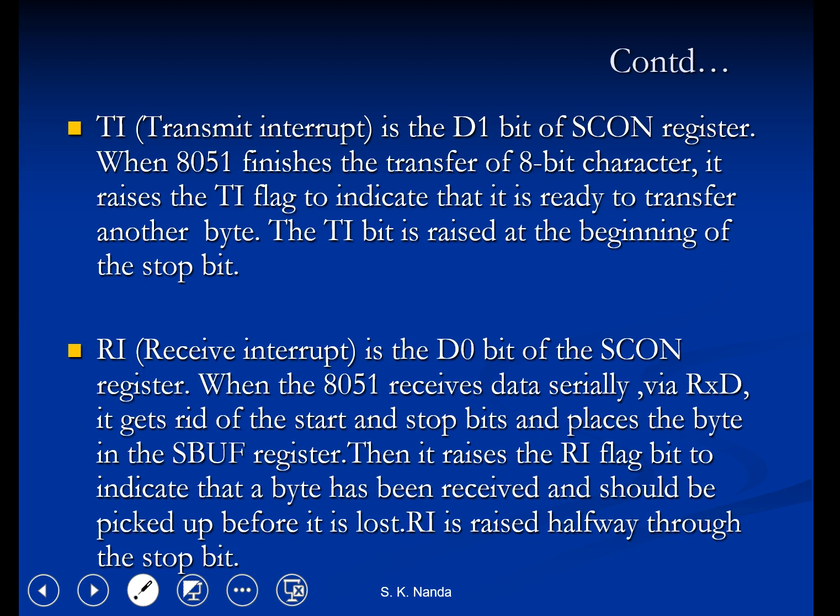Then TI is the D1 bit of the SCON register. When the 8051 finishes the transfer of an 8-bit character, it raises the TI flag to indicate that it is ready to transfer another byte. The TI bit is raised at the beginning of the stop bit.